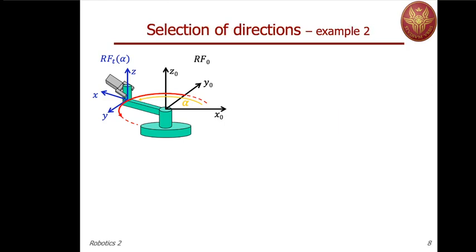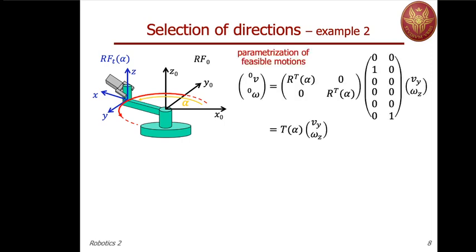Now, even in this second example, we can parameterize the direction of free motion and parameterize as well the direction where the environment is producing reaction forces or torques. We will use again the formulas with the T and Y matrices, but now we will have a slight change because we are in fact having a task frame which is rotating with the angle alpha.